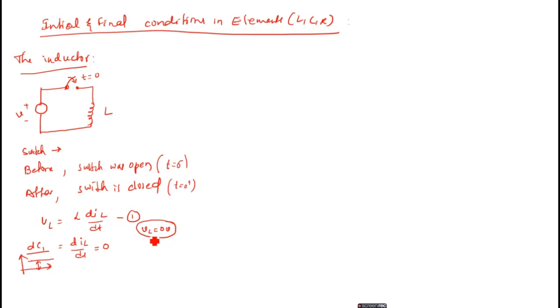Next, let us calculate the current through an inductor here. So from this equation, can I calculate I? I is equal to 1 by L into the integration from minus infinity to t of V into dt. Means apply integration on both sides. So this integration and differentiation will be cancelled. What is remaining here is the integration of VL divided by 1 by L.